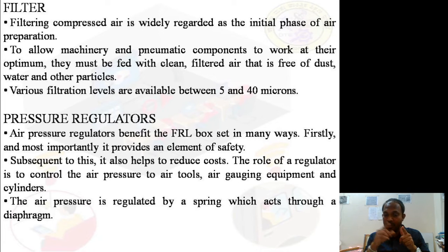That air might also come out with some moisture content because of the drop in the dew point. What comes out is subjected to filtering once again. This filter will not only filter the solid particles, but also reduce the small amount of moisture content.